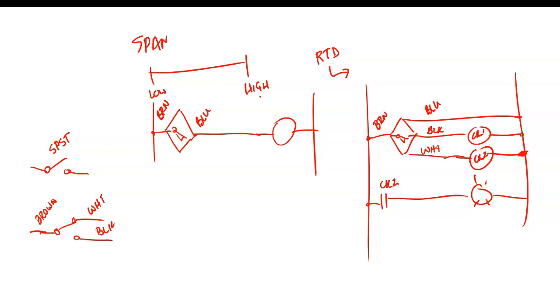So it's like your 2-level that you're doing in your lab, where you use 2-level sensors, where you run it till it gets to a certain height, then you cut it off, and then you run it till it drops down, right? So what you're doing is you're setting a range within which that tank would hold its water. 2-level control. So we have 2 adjustment barrels on there that we turn to set the upper limit and the lower limit, where you want it to trip on and where you want it to trip off.